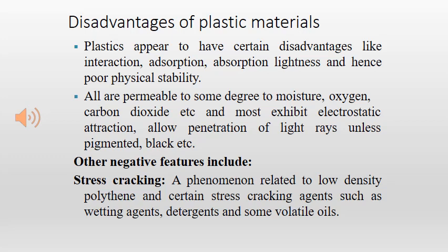Then comes paneling or cavitation. Paneling occurs when the pressure inside a plastic bottle becomes less than the ambient air pressure outside, causing the walls of the bottle to partially collapse inward. The result is an aesthetically unappealing product package with a distorted shape and badly wrinkled labels.